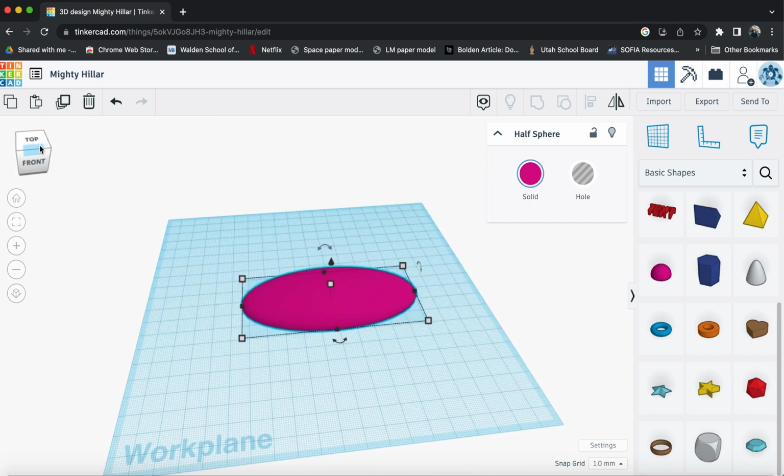There is, however, one thing that you need to know here, and it took me a while to discover it, but there are times when you do not want to see this scene in a perspective view, where you see that the edges and sides of the work plane converge to a vanishing point on the horizon. That's the way of showing perspective or 3 dimensions on a 2-dimensional surface, my computer screen. But there are times when you only want to see it in 2 dimensions. And that's if you want to align things precisely and make sure they're exactly in the right position.